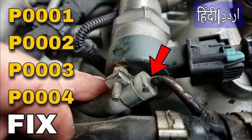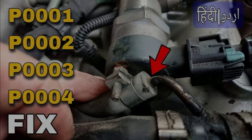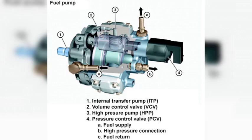To diagnose the P0002 code, you will need to use a scan tool to access the ECM data. The scan tool will show you the current fuel volume regulator position and the desired fuel volume regulator position. If the two values are not the same, then there is a problem with the fuel volume regulator control circuit. Once you have diagnosed the problem, you will need to repair it. This may involve replacing the fuel volume regulator, repairing the wiring or connectors, or replacing the ECM.